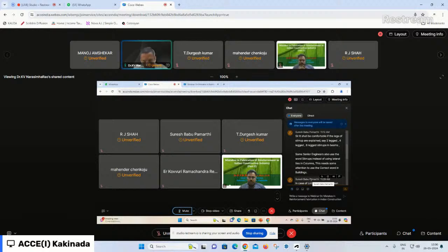Why? Because your fixity conditions or rigidity conditions will be effective and take place only when there is the full development length of the steel. Once you are not providing a full development length in the anchorage zone or the compression zone, where the bar is to have the full tension mobilized, there is always a condition that leads to partial fixity or no fixity. If the development length is less than Ld by 3, you can have a simple support connection at the beam column junction. That is the case. Especially from the seismic resistance point of view, the beam column junctions play an important role in transferring the shears and the moments.